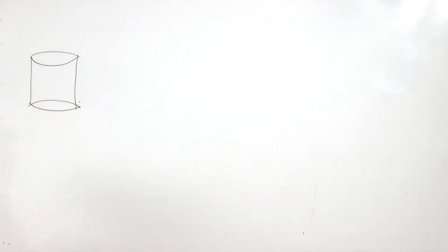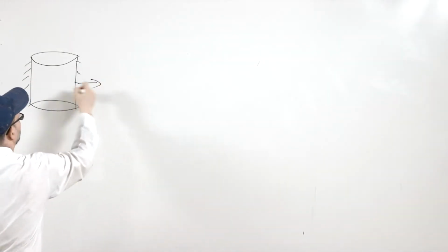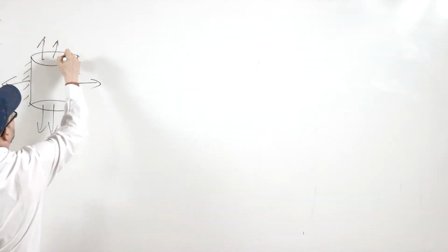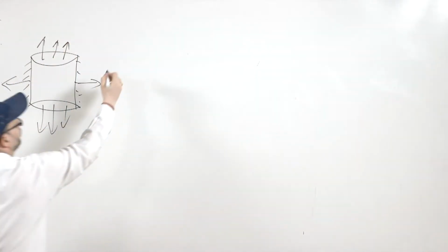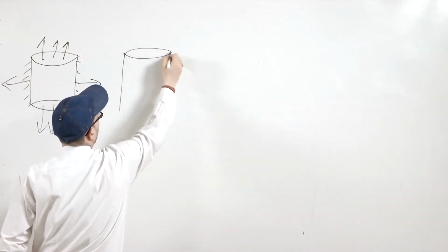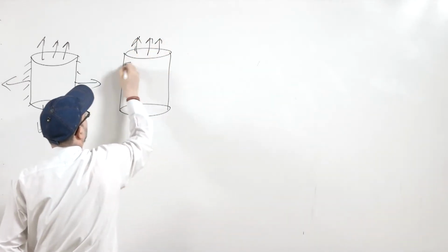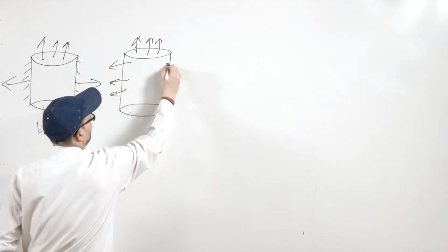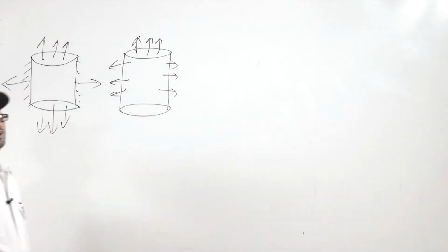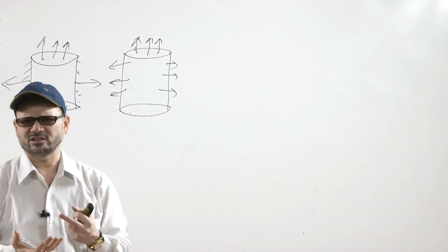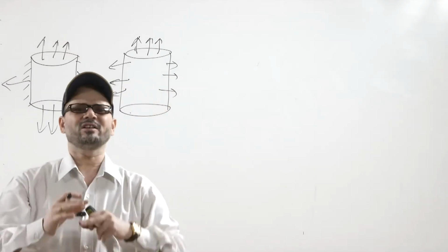Now, you can have the condition whether you allow all the portions to extract heat. Many times, all the surfaces extract heat, but not from here, because we assume that the bottom part is in touch with the casting, either the top riser or even the side riser.